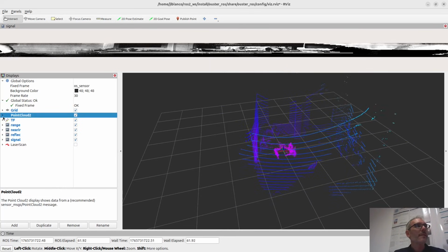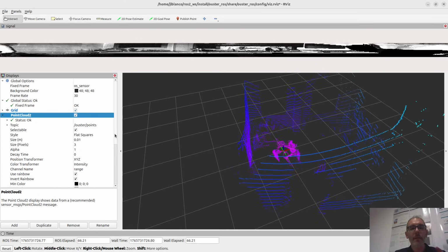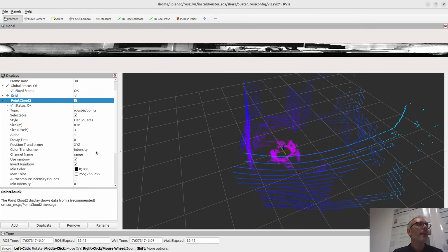If you want to check, this is important, I want you to check that we have the right fields inside each point in the point cloud. Because for accurate motion compensation in LiDAR inertial odometry, we need each point to have X, Y, and Z, intensity, and so on, but also the timestamp, the relative timestamp of the point inside the cloud.